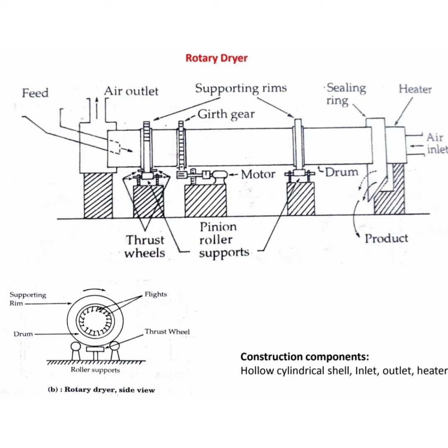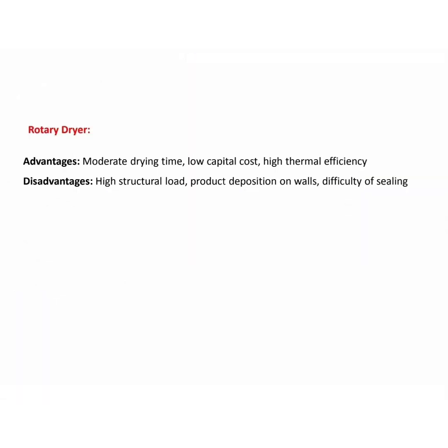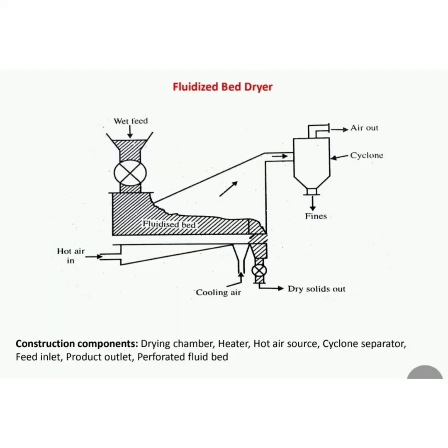Finally, the air leaves the dryer. The dry product is then taken outside. Advantages of rotary dryer: moderate drying time, low capital cost, high thermal efficiency. Disadvantages: high structural load, product deposition on walls, difficulty of sealing. Now let's see fluidized bed dryer.